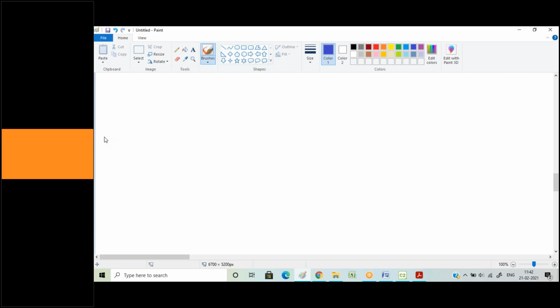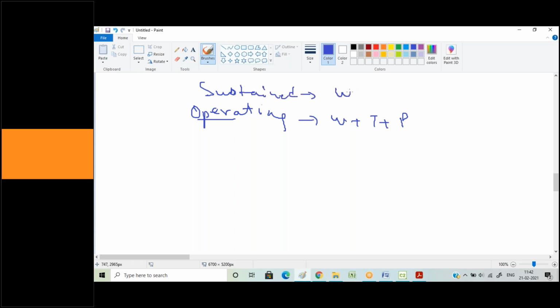Now, quickly I'll explain one more thing over here. One is the operating condition, and the next is expansion. Operating is basically your W plus T plus P, whereas for your sustained, I might have told you, but I haven't told you about the load case. Your sustained is W plus P.